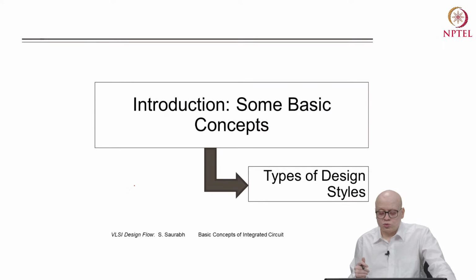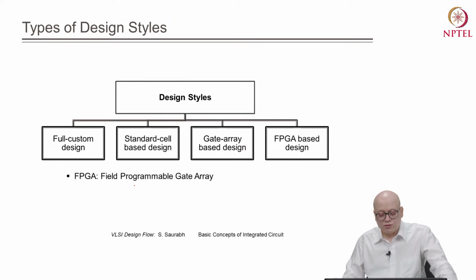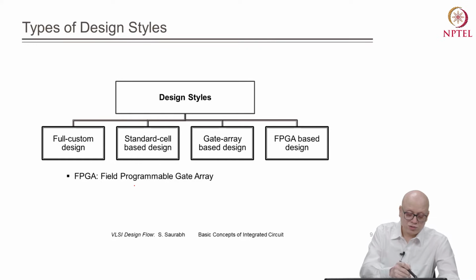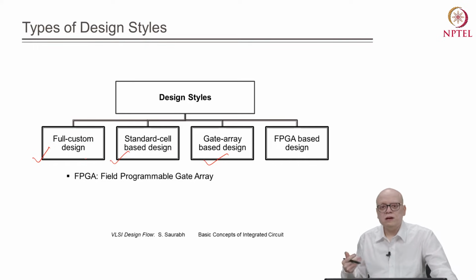Now let us look into what are various types of design styles. So based on the types of design styles, we can categorize integrated circuit into full custom design, standard cell based design, gate array based design, or FPGA based design. FPGA is short form for field programmable gate array. Now we will be looking into each of these 4 types in more detail.